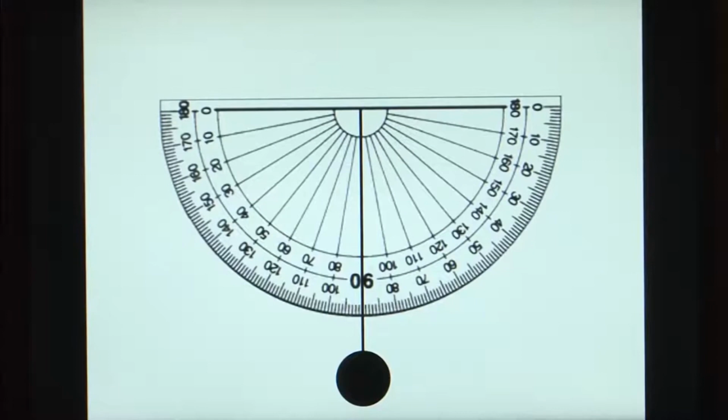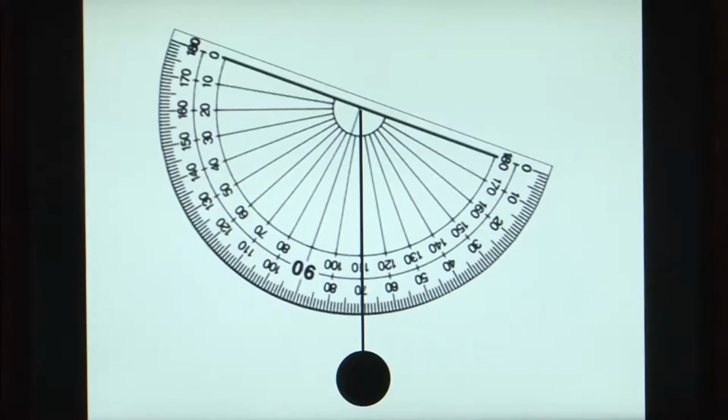So what we have done here is we have taken a protractor and right through its 0 point we have drilled a hole and we have put a string through it, and on that string we can suspend a weight. Now if a weight is suspended, then this string is always held vertical. So now if this protractor is moved to measure any angles, it can be used. So let us now see how it would look in practice.